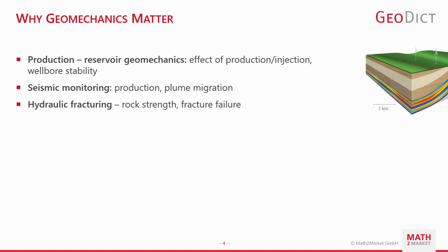Furthermore, one also application of knowing of geomechanical properties is regarding the hydraulic fracturing, where you directly have to know the rock's strength, its failure stress state, and that it helps to effectively predict when will the rock fail, and how will the fracture propagate. So all of those are some quite important questions to be resolved, and there is why geomechanics helps.